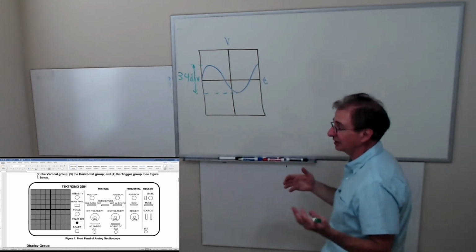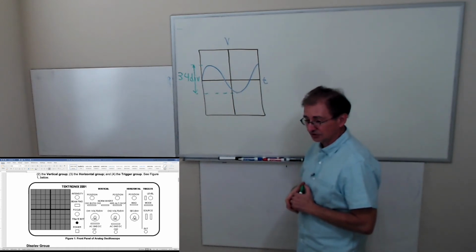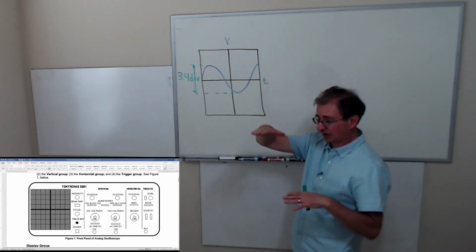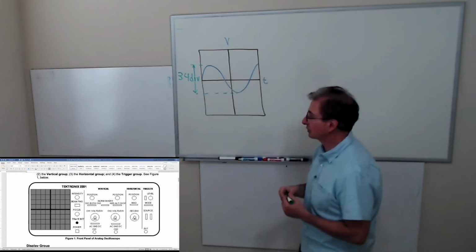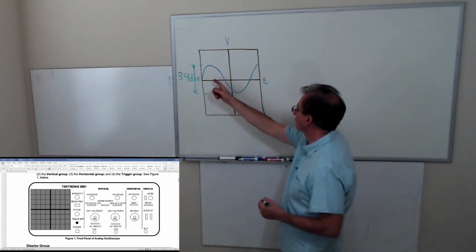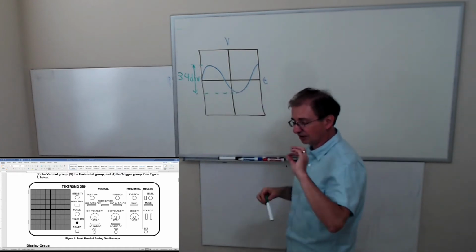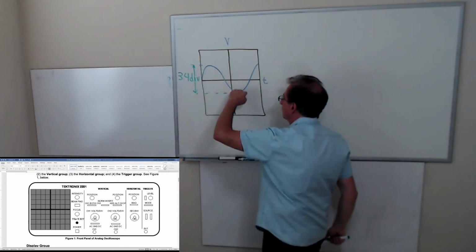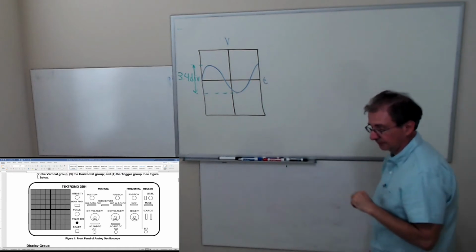In the case of the CRT scope with the electron beam, it's basically changing how much the electron beam deflects from this point to measure voltage. If this was an electron beam, it would be scanned across the screen. And when it hits the screen, the screen's phosphorescent, you see a green line. And it scans it very quickly.